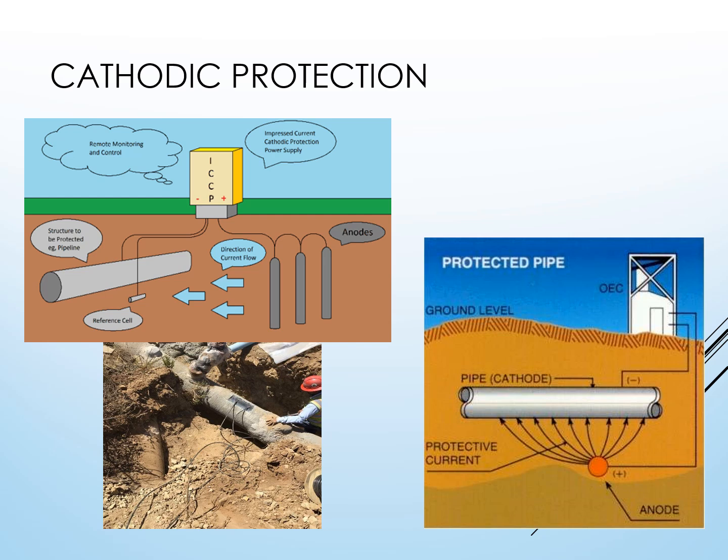Cathodic protection. This is a science in and of itself. It's using what we call anodes to protect steel pipes from premature corrosion. Like I said, there is a science behind cathodic protection: installing the right number of anodes, the right size of anodes, the right type of anode. It all has a factor in it. You have stray currents that are potentially going to eat away at the steel on pipes. And so that's why, like I said, you cover them in concrete to help add that extra layer of protection.